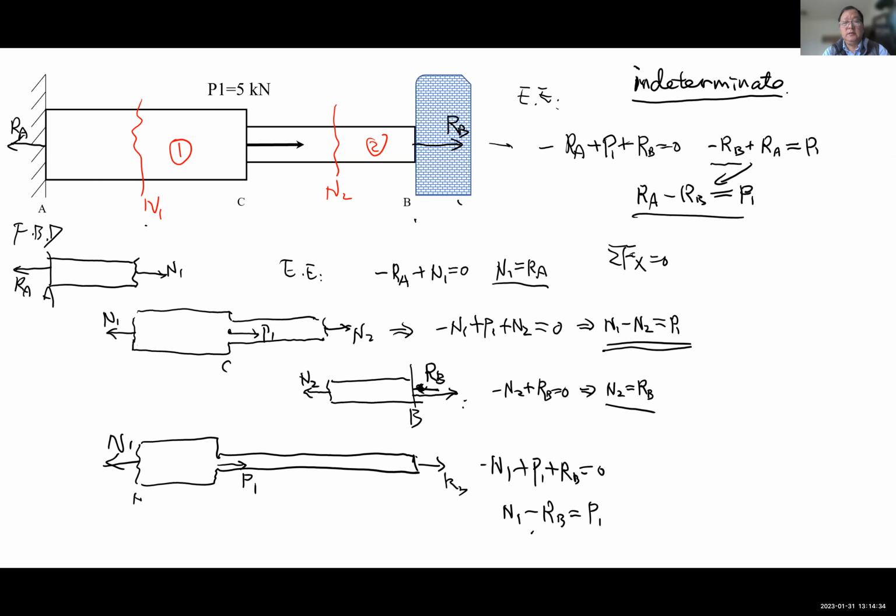All right, so that's the definition. We're going to talk about more next, but here are two things. One is why have this indeterminate. That's because when you build a structure, you oftentimes want more support, more stability, or for functional purposes. You want to build a bar between these two walls, right? So people can pull or connect it, or can walk like on a bridge or something. So there is either a functional need, or you add additional support to make the structure stronger.